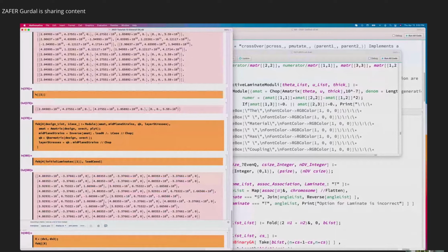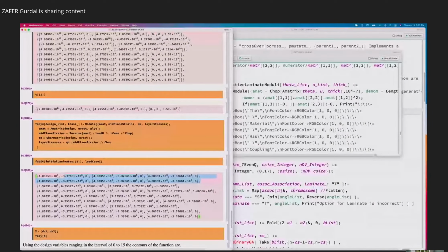These are the ply level stresses for the first design. So you can see that the first 6 plies have the same stresses. Third one is plus 60 and minus 60. And then another plus 60, another plus 60, and another 0 and 0 here. So these are the different ply stresses. I am not done yet.